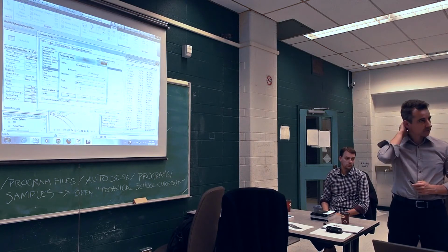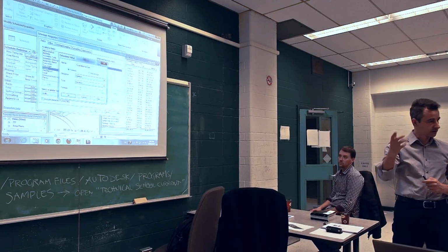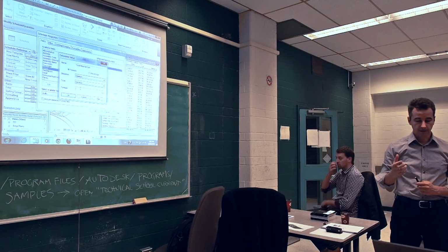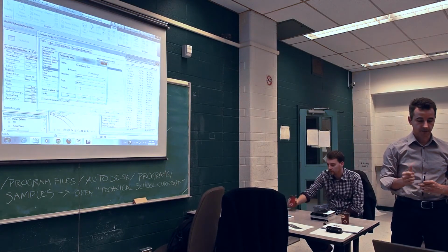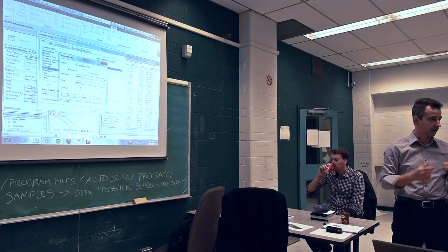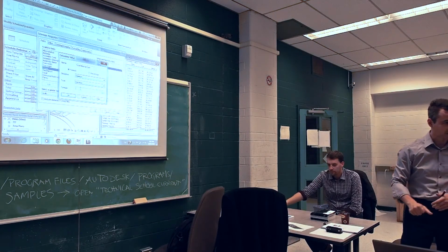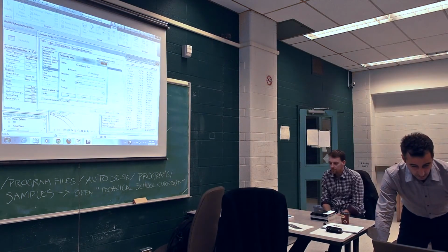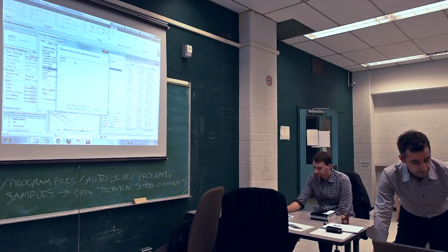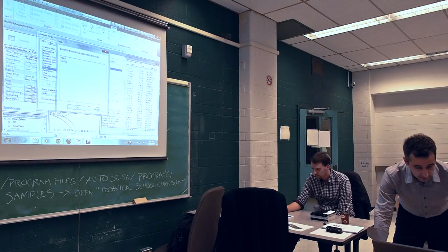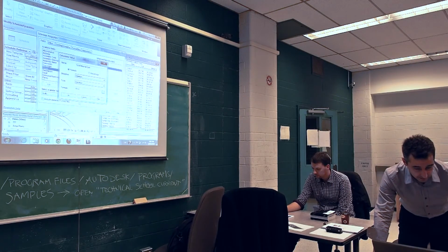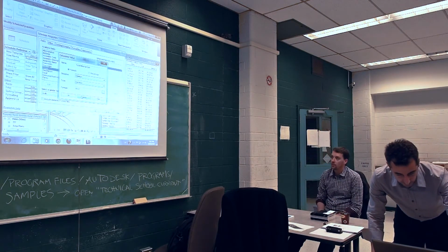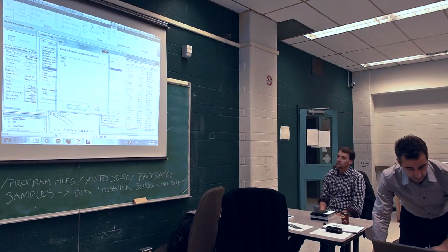And I believe starting with 2012, you can actually choose fields because it's very strict in terms of uppercase, lowercase. If you mistype, that's even worse, right? So instead of typing, you can go here and choose from the fields that you can use in this formula. So area, and then multiplied with the cost,